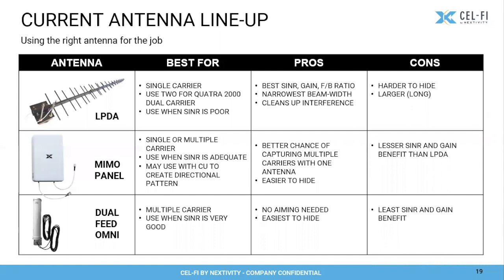So for example, if I'm pointed at tower A, which seems to be better during the day, and at tower B, which seems to be better at night, and I need 24/7 service at this site, I would honestly want to run a test. I would certainly try to point an antenna in each direction, sum them together, and bring them down into the system.